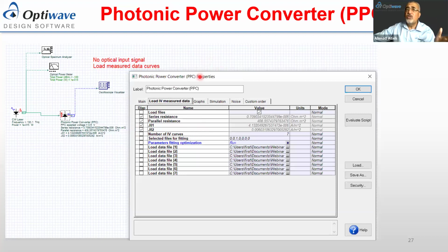Now, this component can be used mainly in power beaming applications, where you can, for example, power up high altitude balloons or a remote radio head where you don't have electricity. You can shine a laser onto this chip and convert it to current. It's exactly similar to a solar panel, but using laser light.